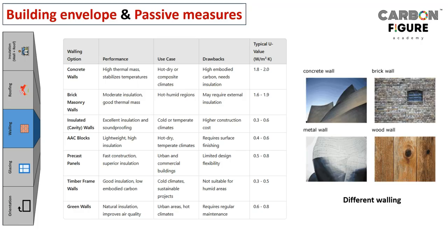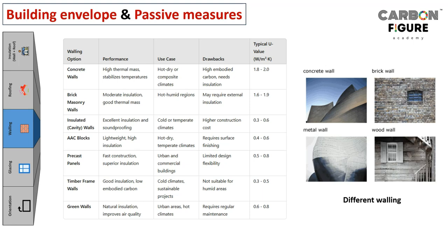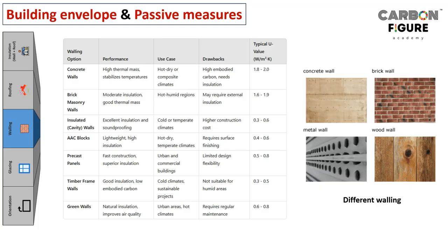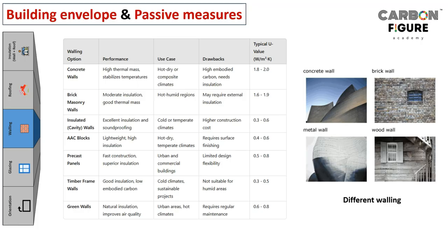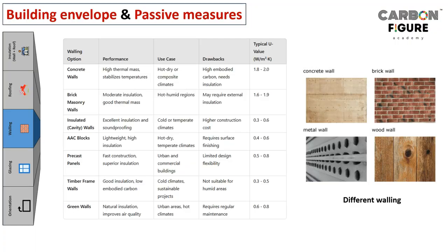In cold or temperate climates, these can be preferred, and it comes with higher construction cost, because you have to tell the people to keep the space throughout the external walls. Instead of following a typical fast wall erection, here you have to keep it slow, and you may need to lose some internal space as your external wall thickness becomes more.